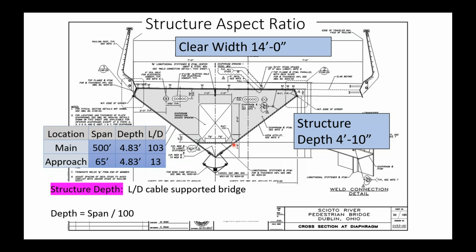As far as fracture critical, yeah, the bridge does have fracture critical elements. Those were identified on the plan set as such, and a detailed welding quality control plan was developed. This bridge was fabricated at a shop in Florida, and those fracture critical elements were inspected to the higher standards that requires, as well as the details were developed to the fracture critical standards and identified on the plans as such.